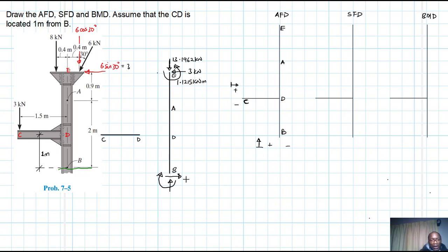Okay, all right. For this particular beam where we have this applied force here, which is 3 kilonewtons, we expect to have a shear force at the very end here, which is also going to be equal to 3 kilonewtons. And because this is going to cause a moment in this direction, which is anti-clockwise, a moment that will counter that will be anti-clockwise, and this moment is just equal to this.